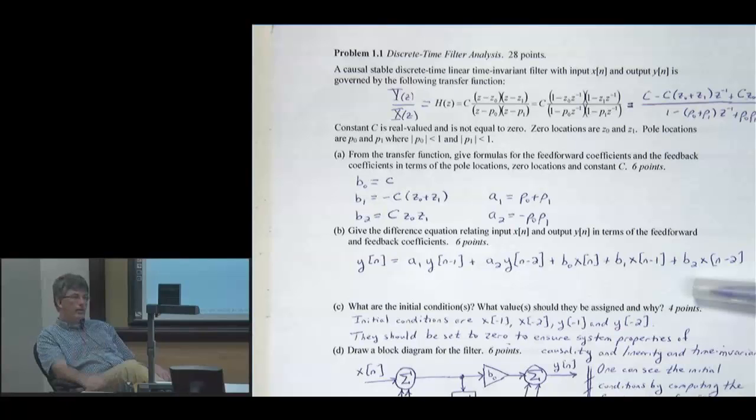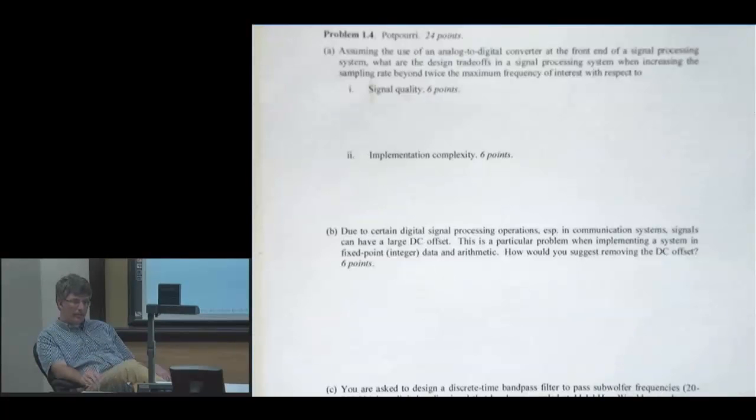Now, what about aliasing in general when I increase the sampling rate? You don't have as much. You're going to have aliasing no matter what, but if we oversample, you'll have less. So I have less aliasing anyway, and I have a better handle on at least some part of that noise. Between the maximum frequency I care about and half the sampling rate, I now have a better handle on what to do with that noise. We're going to use oversampling like crazy coming up. Love oversampling.